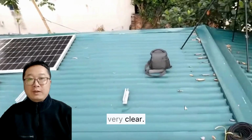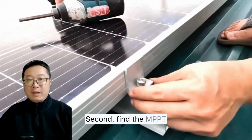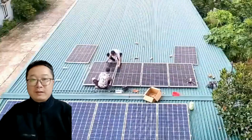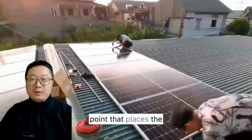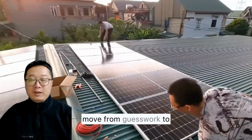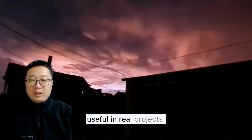So the method is very clear. First, find the safety limit. Second, find the MPPT window. Third, narrow it to the real integer range. And fourth, choose the point that places the string near a better operating voltage. That is how I move from guesswork to a design that is safer, clearer, and more useful in real projects.